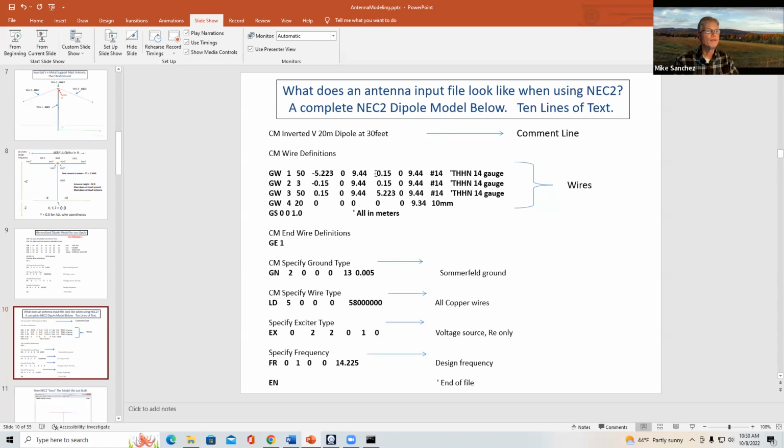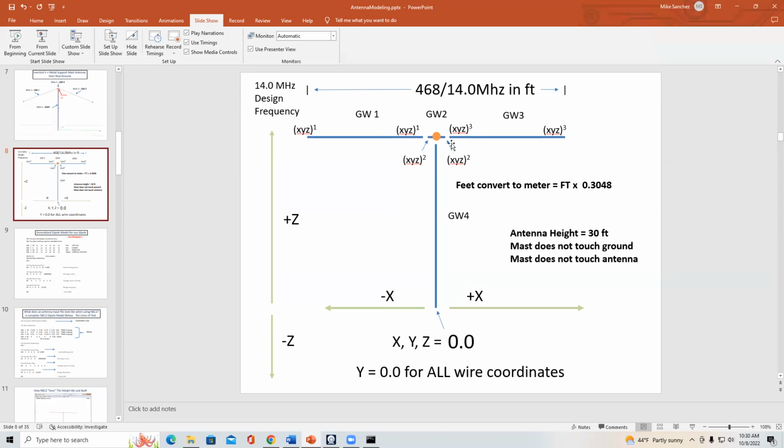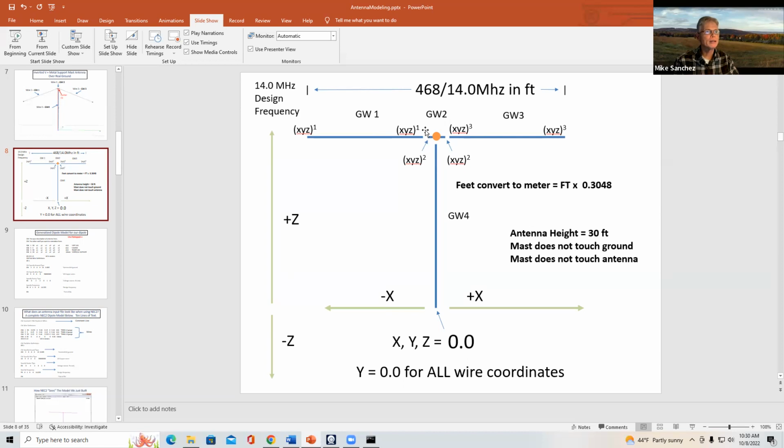For the total length in here, which you then divide by 2, one for the right leg and one for the left leg, you can pick anything less than 0.1, 0.3 meters, basically. Does that help? In this drawing, Yen, I have shown a gap here to make it clear there are 3 segments. The antenna actually does not have these gaps.